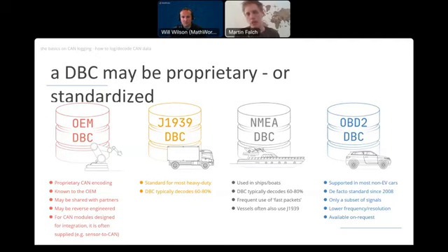However, there can be exceptions to this. If you have a manufacturer of a sensor, for example, that is connected onto a CAN bus, that manufacturer may, as part of the business model, be willing to share the DBC file because that allows for that sensor to be more easily integrated. And beyond this, there are also a number of common standardized protocols within the automotive and maritime industry where you can decode at least a large subset of the data from the application.